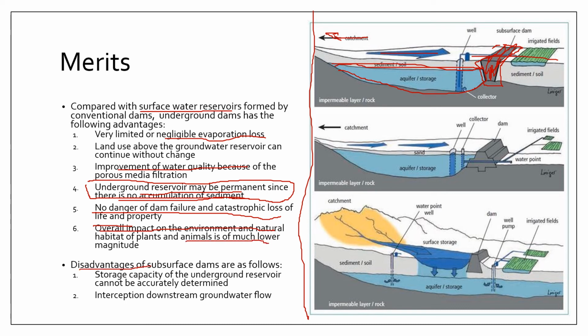Now, the disadvantages of subsurface dams include, of course, that you have a storage capacity that is difficult to estimate, and then you also end up intercepting groundwater flow downstream. So, if you have wells downstream of the subsurface dam, they might end up having reduced well yield.